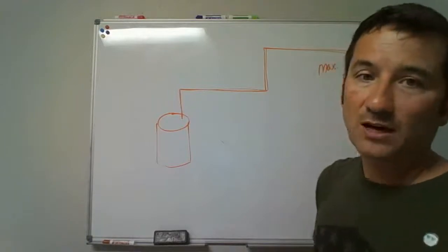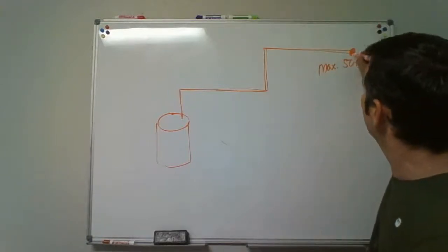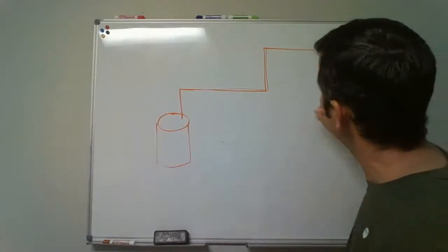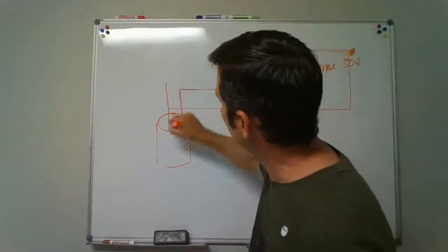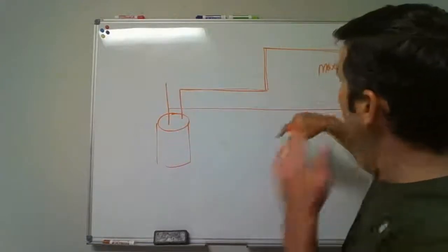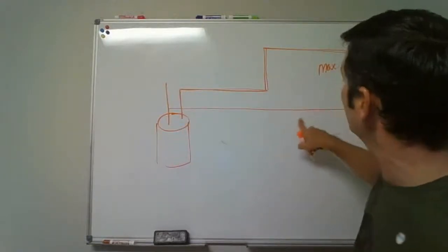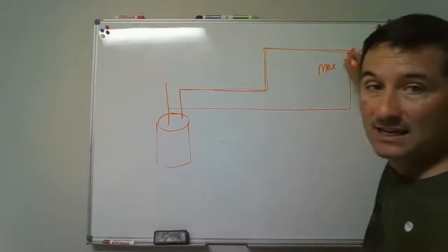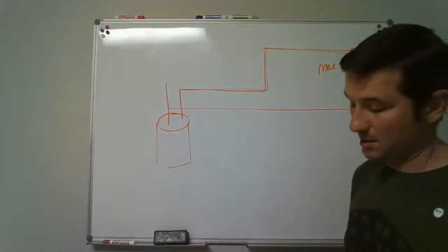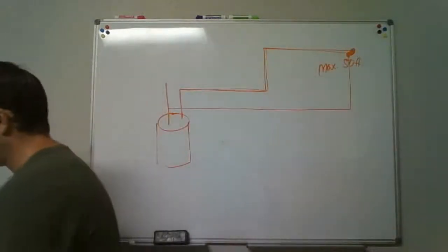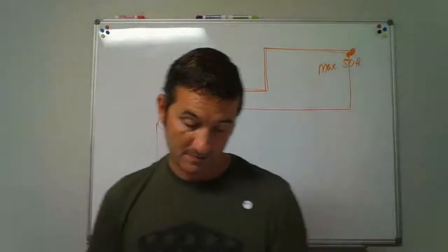Now it says if you run a recirculating line on this and take it off and you insulate that, and you pipe it on back and it runs back and feeds into the water heater to just make a loop again, and you insulate this line, it says that wherever you put that is considered a heat source as well. Okay. All right.